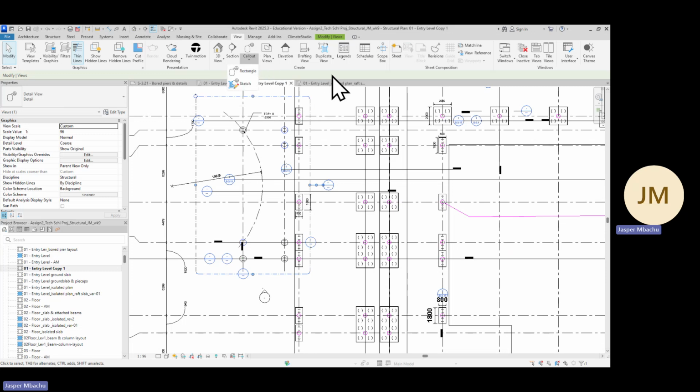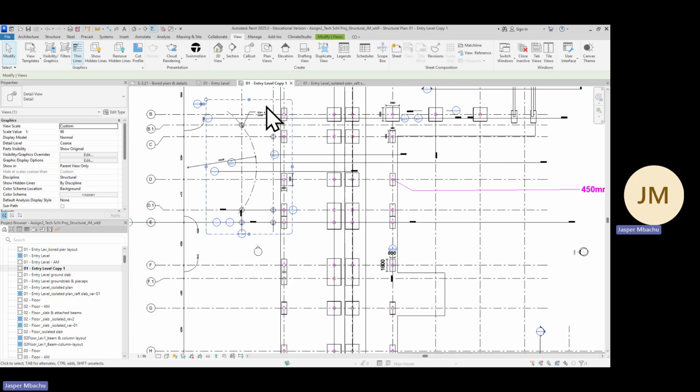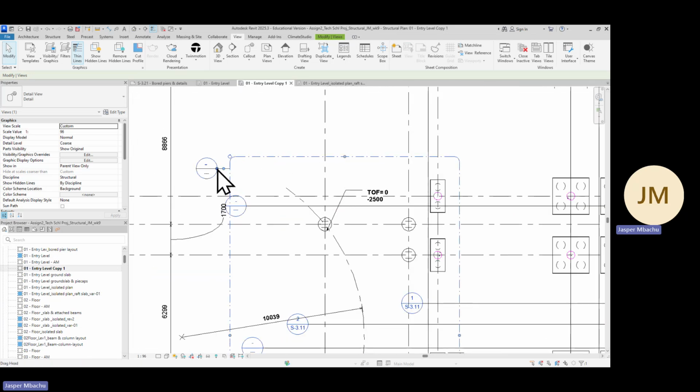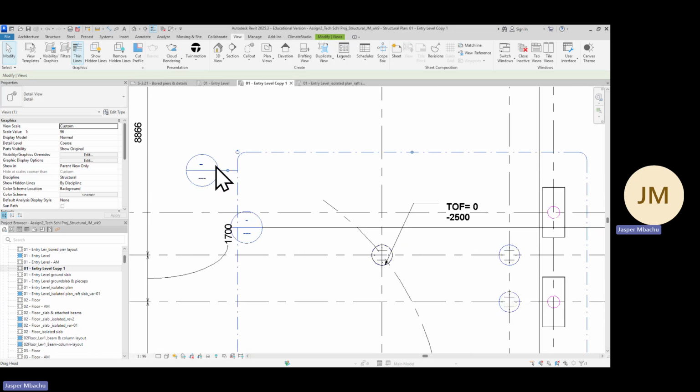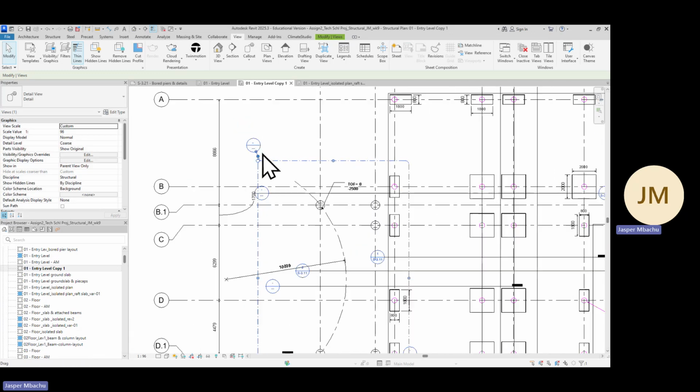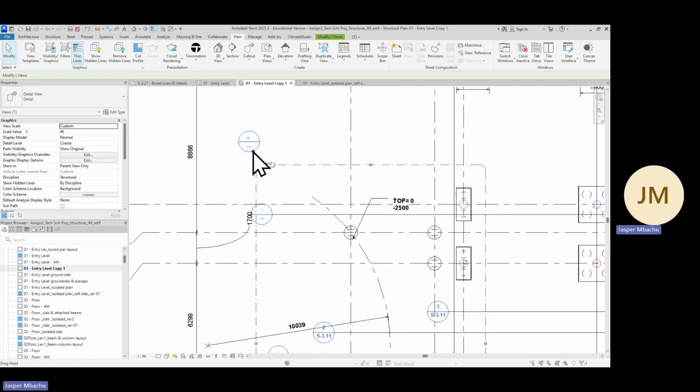Okay. And then when you have got that call out, try to bring the head to a place where it's going to be easily identified. Drag the head, not this one, the one that is in tangent with the circle. That's the one you drag and bring it. Architects and structural engineers like to keep it at a bevel. That makes it stand out, so you're not confused with this.